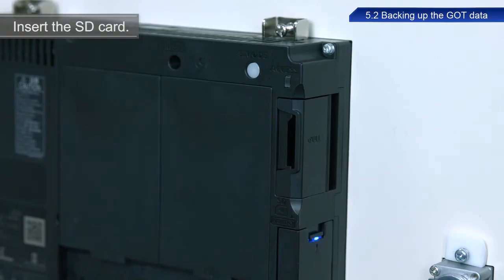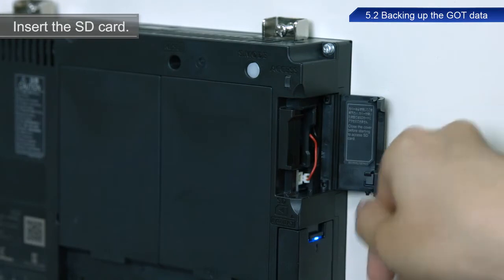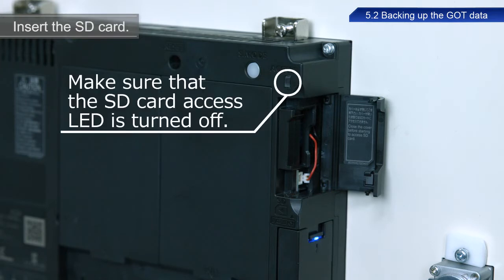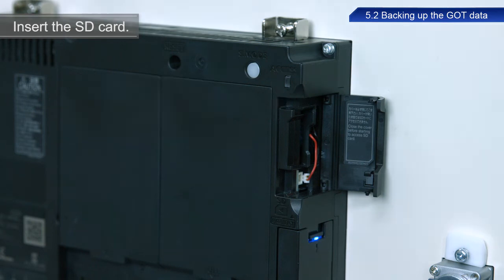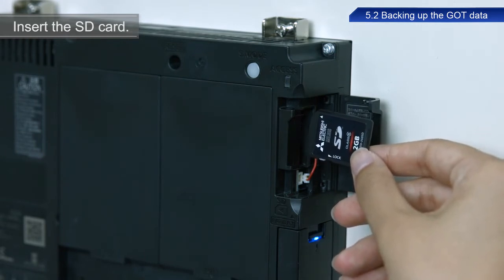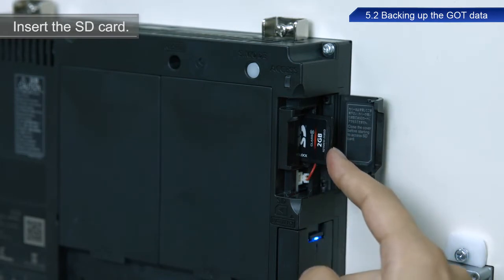First, insert the SD card into the SD card slot in the GOT. As illustrated, open the SD card cover at the rear of the GOT device. Once the cover is open by at least 90 degrees, make sure that the SD card access LED is turned off, and then insert the SD card into the SD card slot with the front side of the SD card facing away from the device.